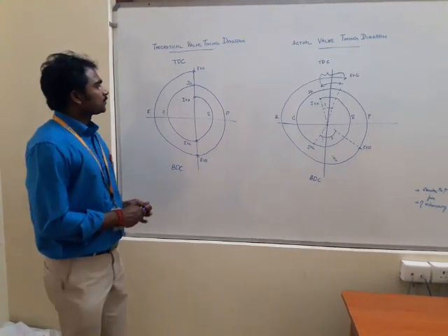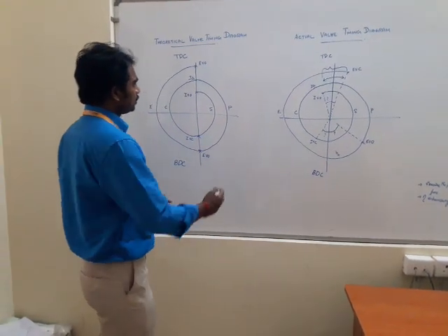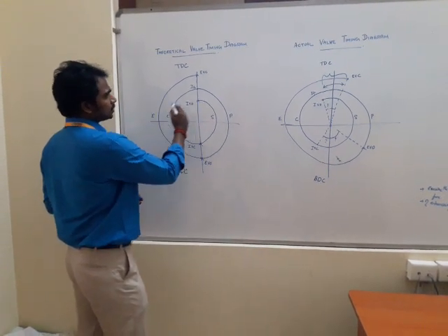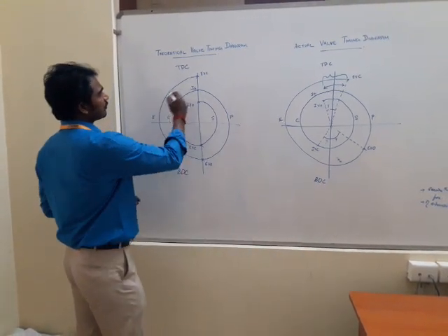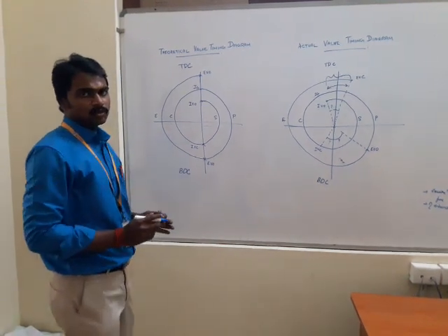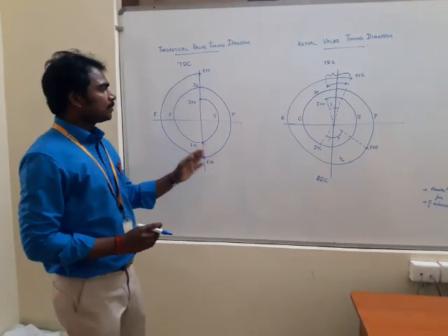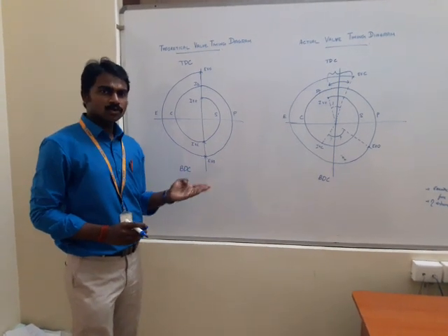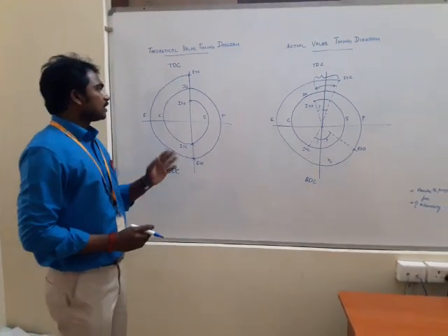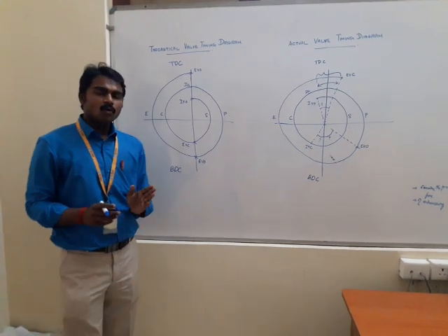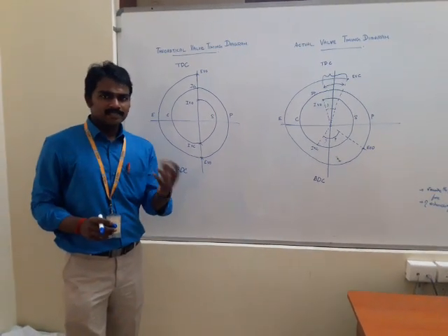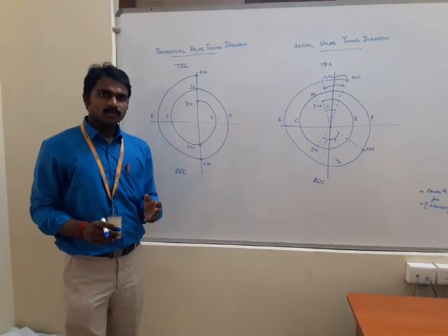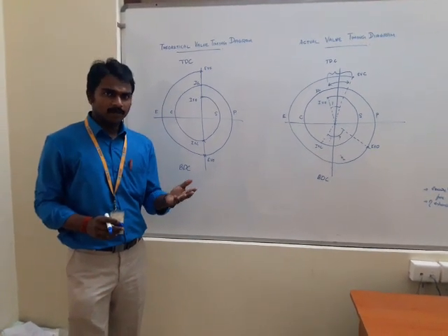The first process in the cycle is suction, followed by compression, then power, and finally the exhaust stroke. All these strokes happen as separate processes, so it is called a 4-stroke diesel engine. Actually, the valve opening and closing is not sudden. It happens gradually. For that reason, we go for the actual valve timing diagram.